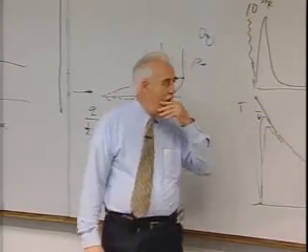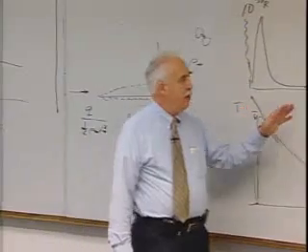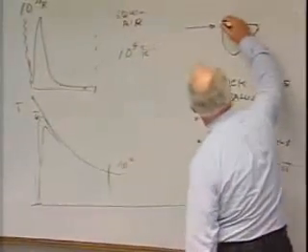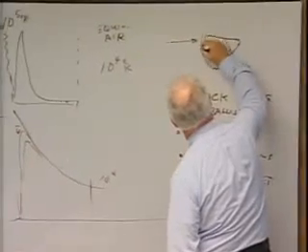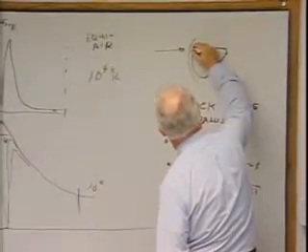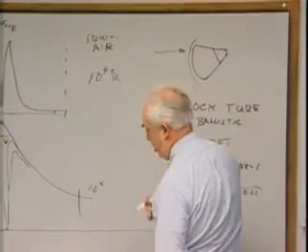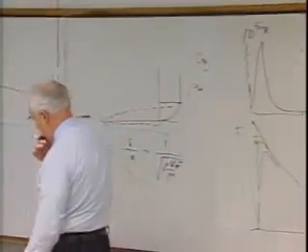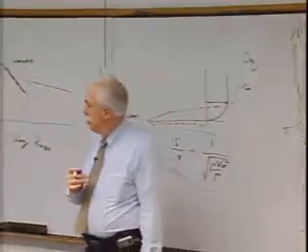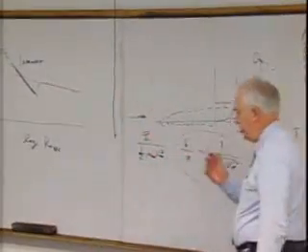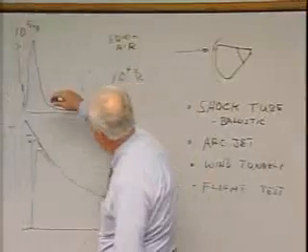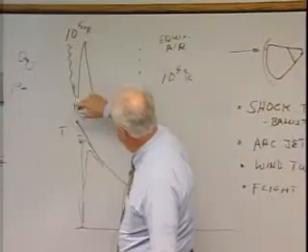Okay, now, as I mentioned before, at peak heating conditions on Apollo, the shock, I can't draw it very accurately to scale, was on the order of about 10 centimeters or 4 inches here at peak heating. Is that the thickness of the shock or the standoff distance? The standoff distance, thank you. Standoff distance. The shock is relatively thin, a few mean-free paths, and all this.